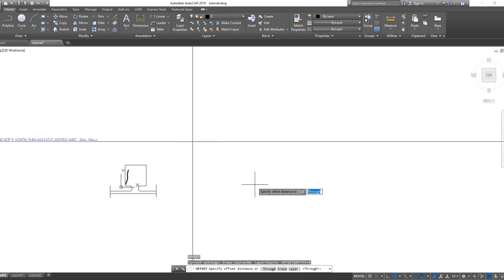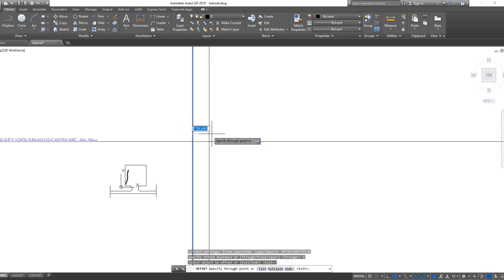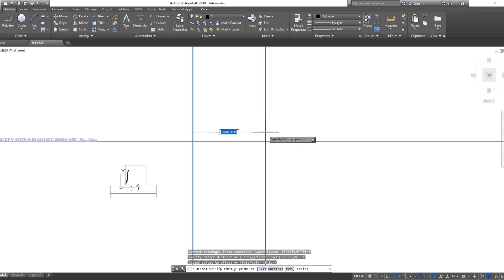So when you are offsetting, if you look at your display window, you can either offset through or you enter your value. So offsetting through simply means you want to specify a distance with your mouse cursor. So I want to offset through, now it's T. So you just move it and you offset through. Though you can see the reading, you're offsetting through without entering a particular figure.